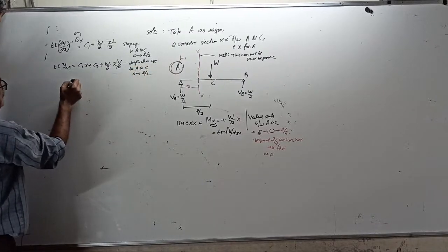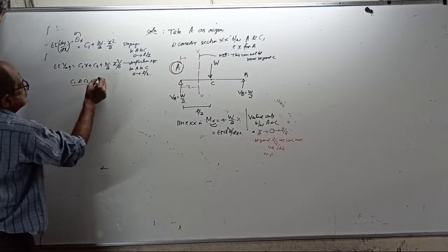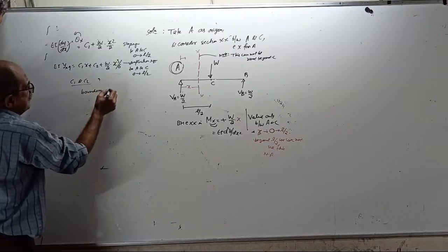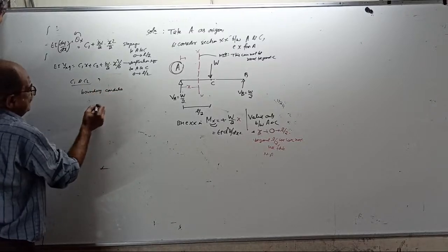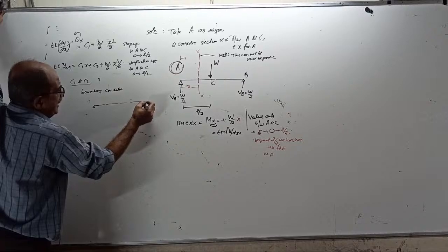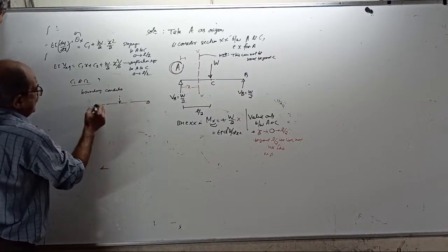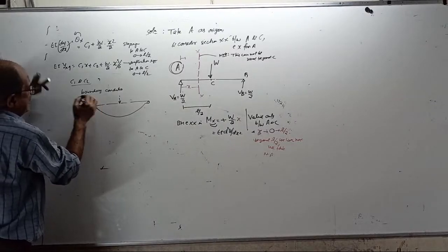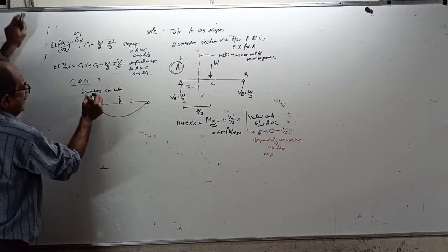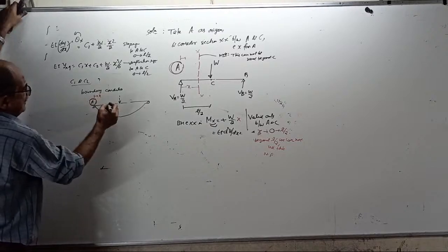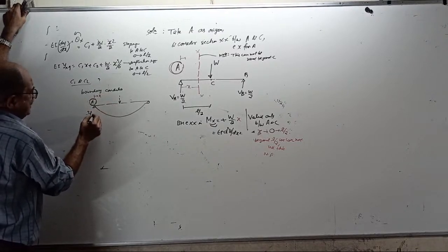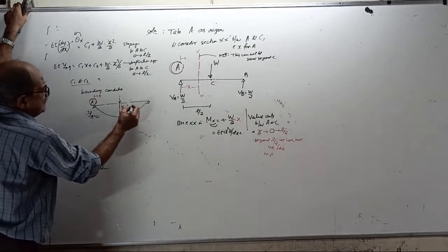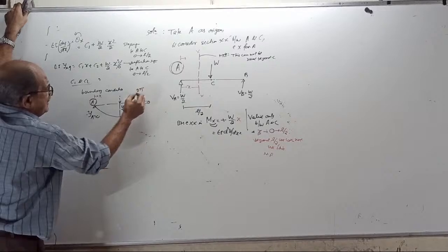Okay, now to get C1 and C2, use boundary conditions. See, the beam is this way, this central load here, the beam will bend this way. At A origin, x is this way. Here, deflection at A equal to 0 and deflection at C is maximum because of symmetry.